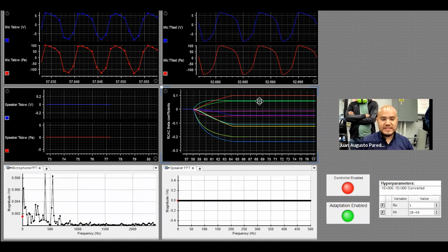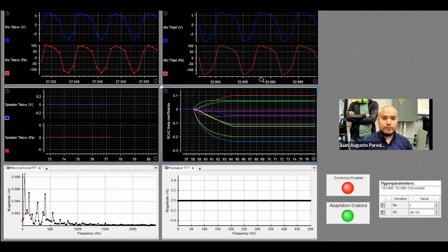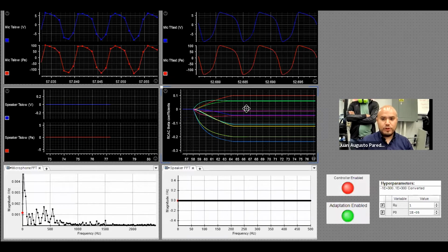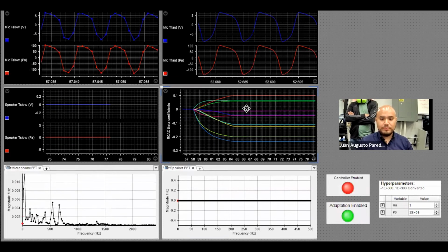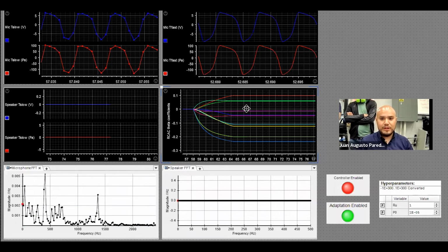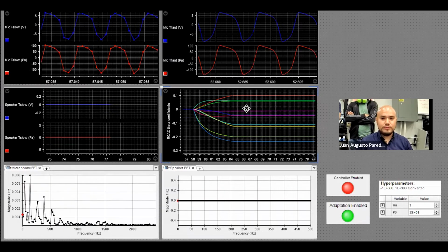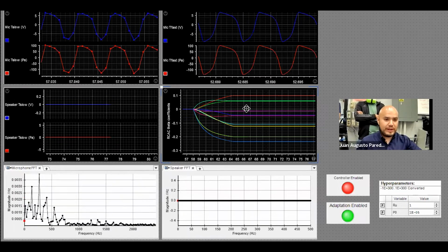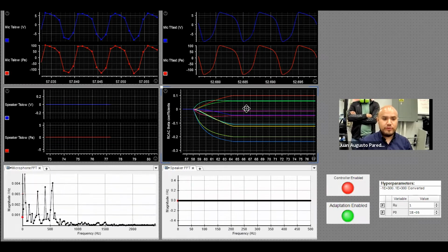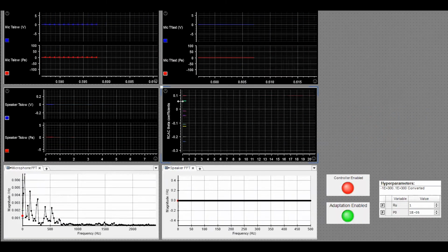Okay. Now, while we were discussing this, John, thank you for your assistance, lowered the coil to a point closer to a fourth of the length of the tube from the bottom. Actually, we're exactly at a fourth of the length of the tube. The tube has a length of 1.2 meters, and right now the coil is at 0.3 meters from the lower side of the tube, which implies that oscillations are going to be more easily formed, and harder to control for RCAC. So without further ado, we'll just start the next test.